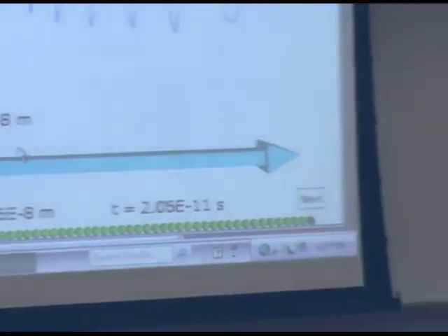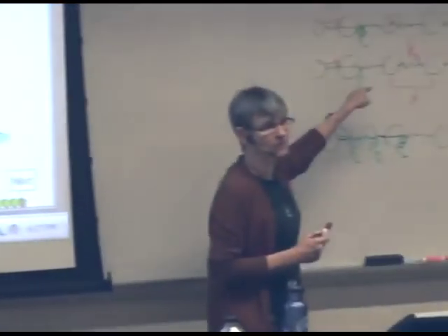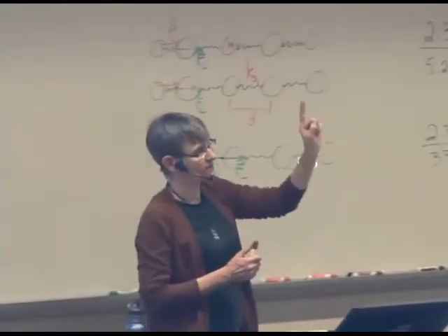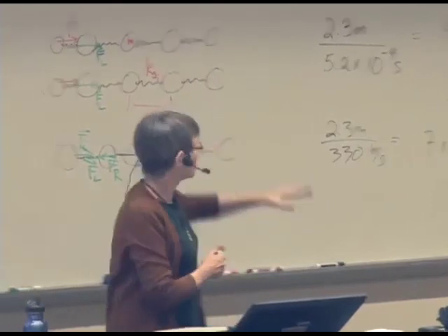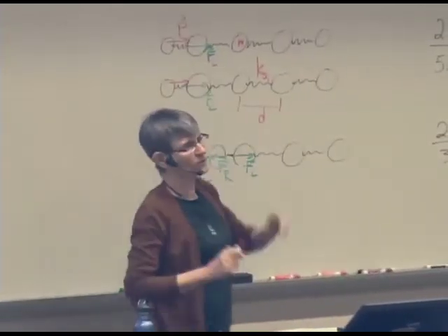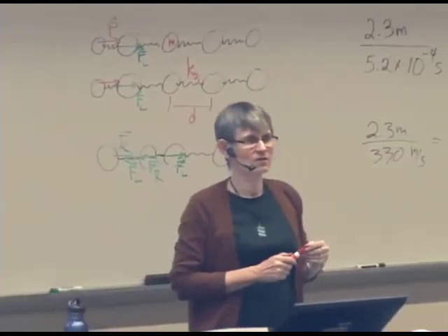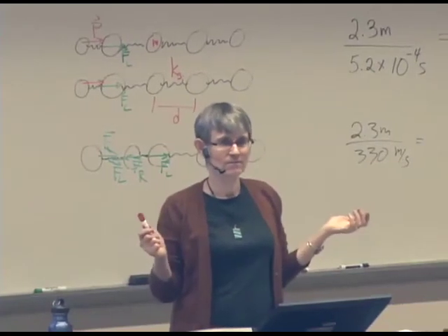So by using exactly the same model, but just using a different atomic mass and a different spring stiffness, which we got from Young's modulus, we're actually able to make pretty good predictions of the speed of sound in solids.